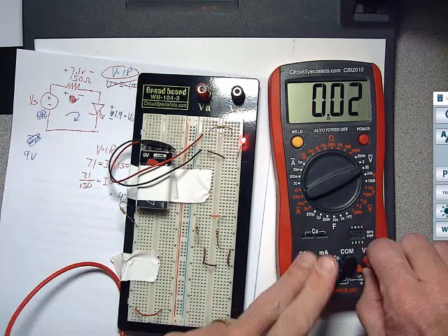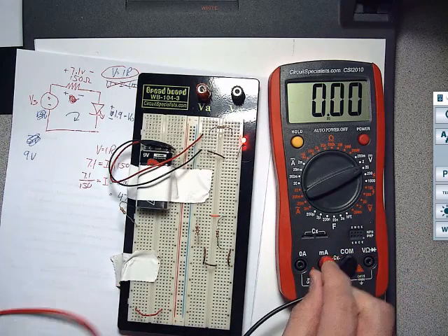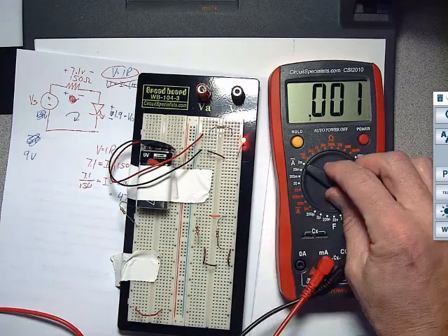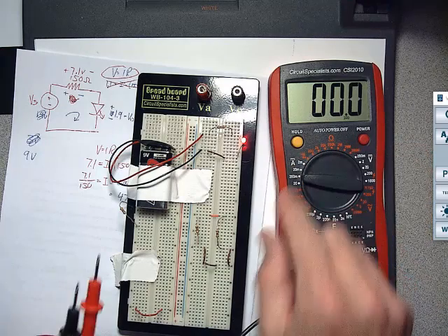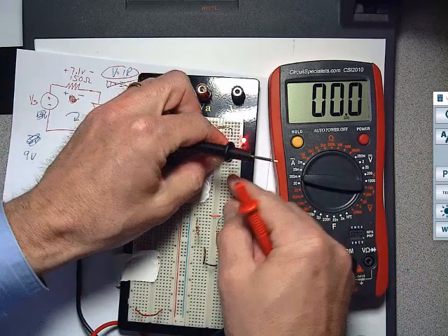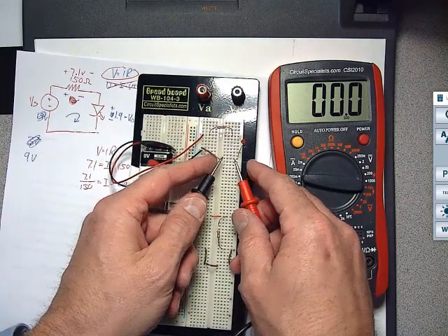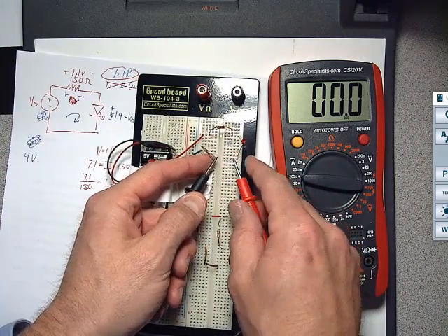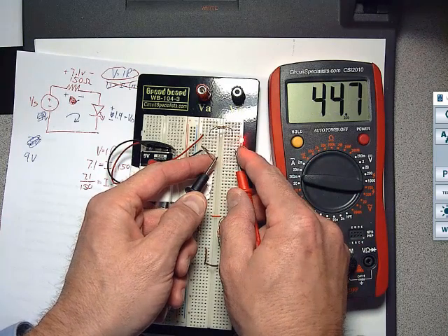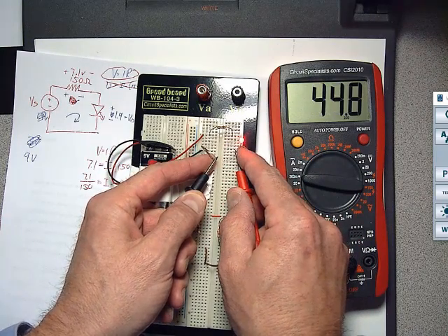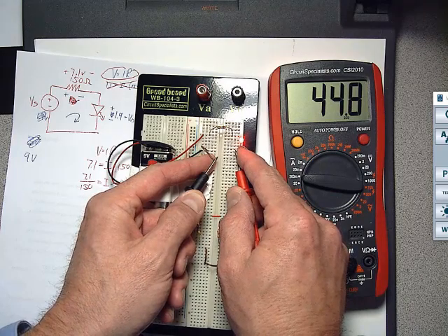So I'm going to take this voltmeter and change it into current mode. I move the lead over there and go back to current with a straight line, and I'm going to say it's no more than 200 milli. I have to break the circuit, and I know that when I measure current, I go in line with it. It's cool with an LED because if you touch it and it turns on, that shows you it's actually conducting. And look at what I got, 44.8 milliamps.